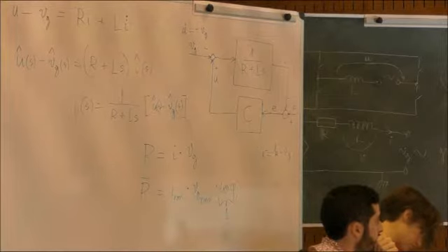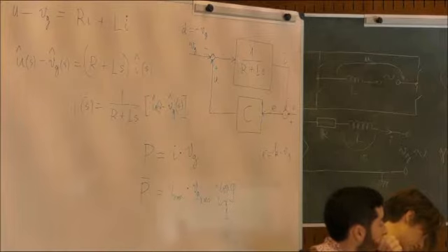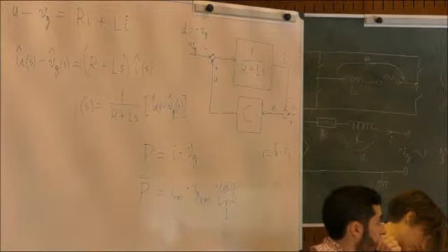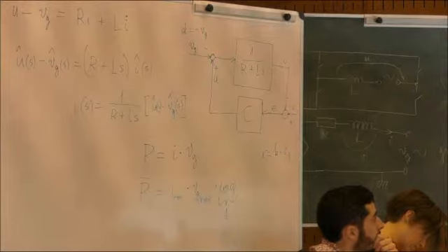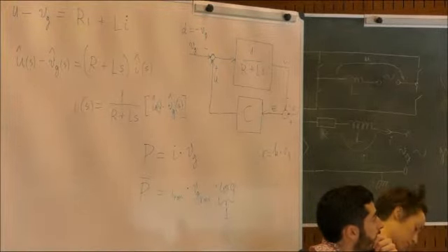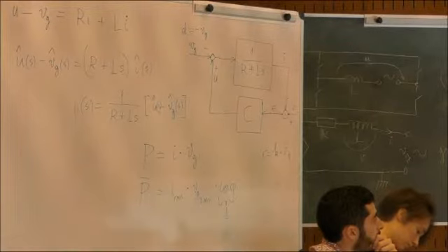It is distorted. And it is distorted because of various consumers who do not act like resistors or like inductors or like capacitors. They act in a nonlinear way. And if you have a nonlinear consumer, then the current that they consume will not be a sinusoidal current. And if the current is not sinusoidal, then the voltage that the utility company gives us gets distorted.